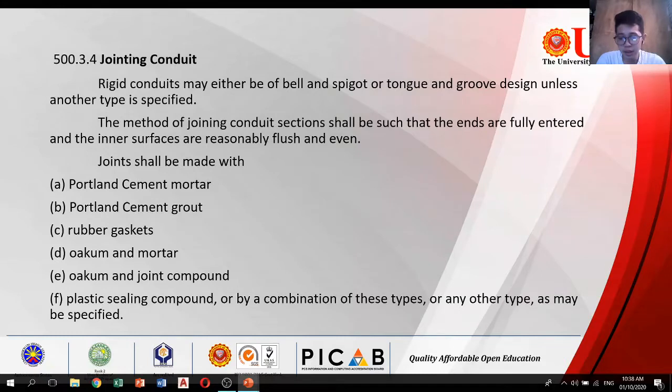So flexible conduits shall be firmly joined by coupling bands, and conduits shall be inspected before any backfill is placed. So any pipe found to be out of alignment, unduly settled or damaged shall be taken up and relaid or replaced.